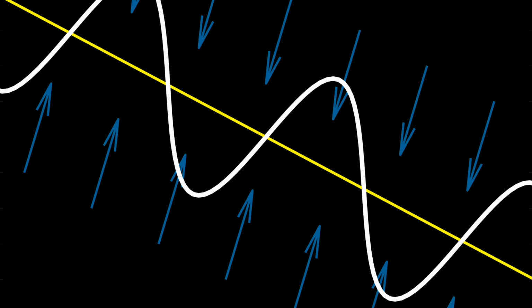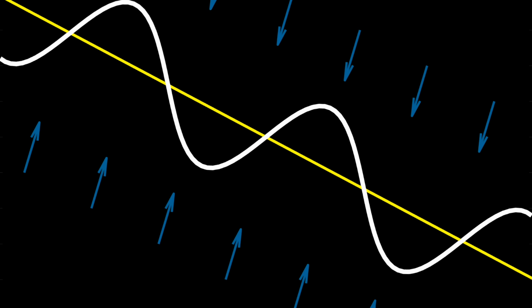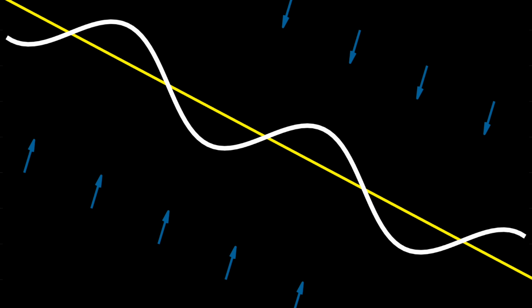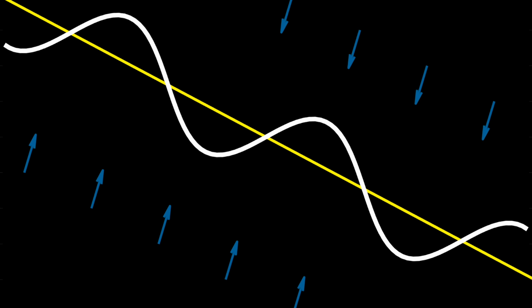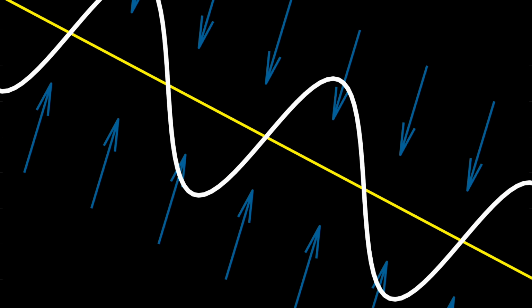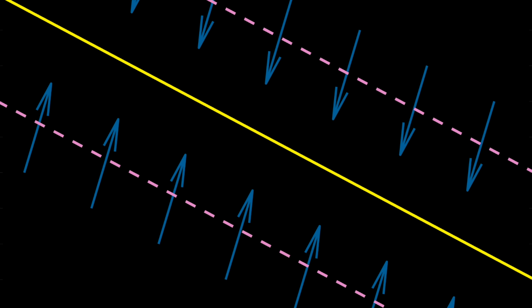Now, if we lower the gain, the controller drives the system less hard around this sliding surface, which will reduce chattering. But as we saw earlier, this affects the robustness of the system. So there's this trade-off between the two. And since robustness is important, we want to find other ways to address chattering other than just lowering the gain. And one way to do this is to define a boundary layer near the surface, within which you can change how the system switches between the two different controllers.